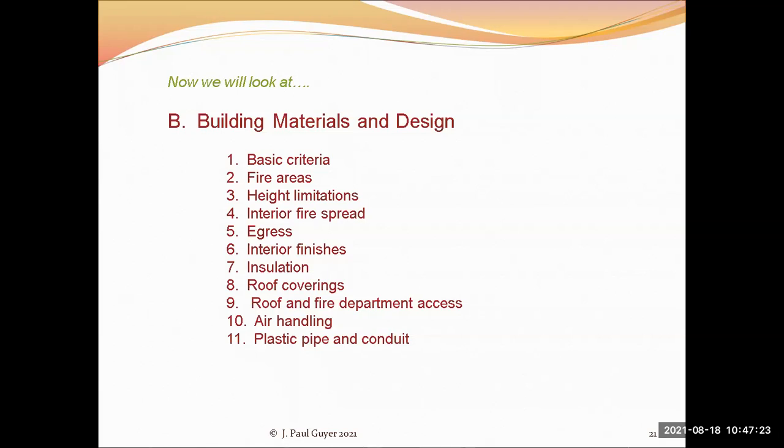Now, another important feature with multi-story buildings is, what floor is the fire on? Well, systems have been developed so that in the event of a fire on an upper story, not only does a local alarm sound, not only is a signal sent to the local fire department, but a signal is also sent to a fire control panel, typically located on the first floor, either just outside the stairwell or within the stairwell.